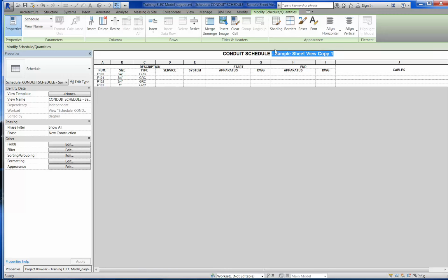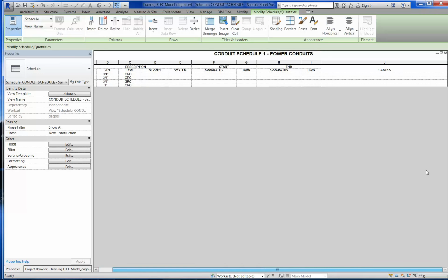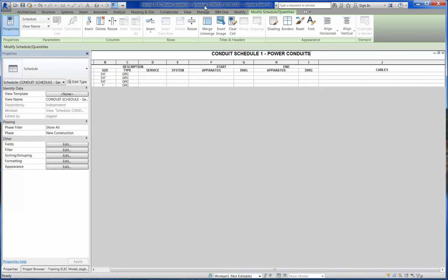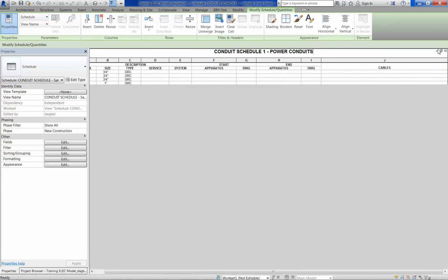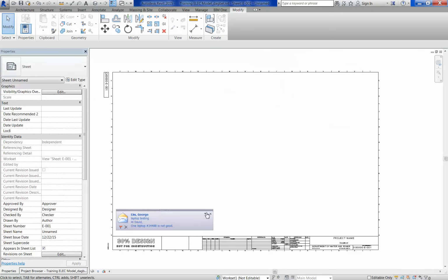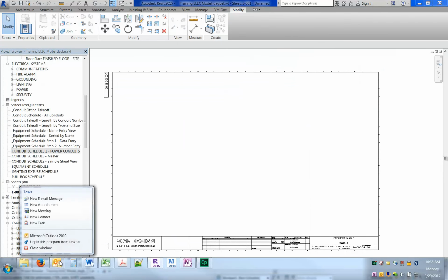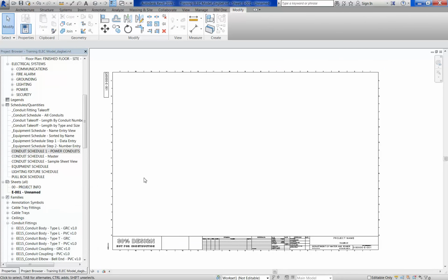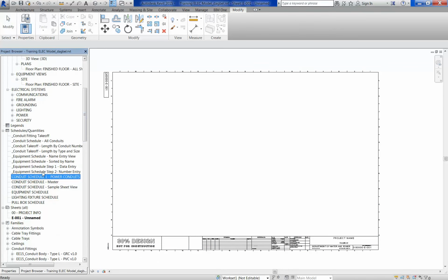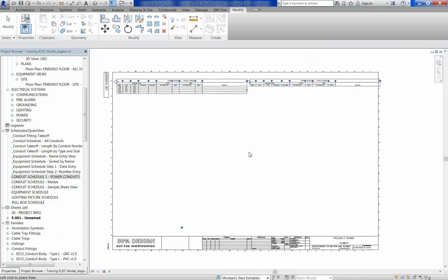We'll call this conduit schedule 1, power conduits. Why not? Close that there. Go ahead and turn off my email so that it's not disturbing the video. So here we have conduit schedule 1, and you just drag it over.